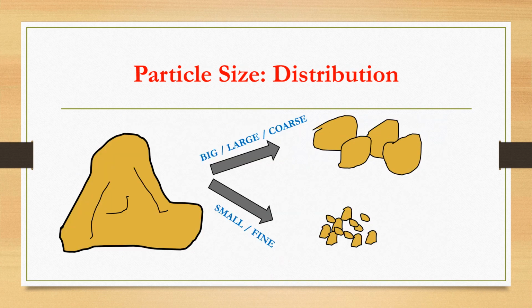In a soil sample, we are interested to know how much of the soil is big particle and how much is small particle. Although natural soils normally are mixed between various size particles, it is common to find a predominance occurring within a relatively narrow band of sizes. Even in a small sample, you have a wide range of sizes, especially for well-graded soil, so you have from big to small. But what we are looking for is the dominance, the dominant type of soil.